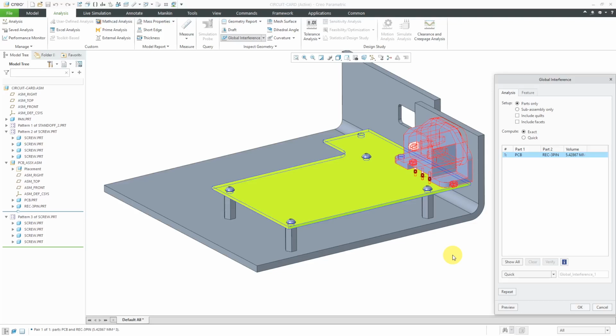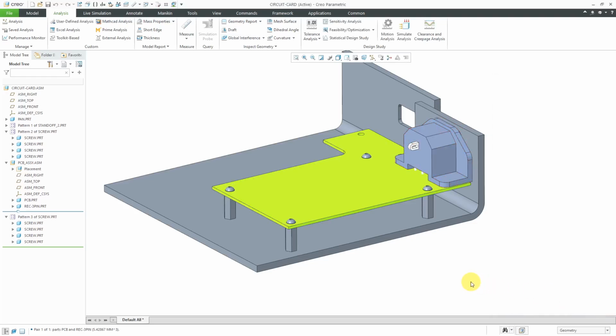Sometimes you want to perform a manual tolerance analysis by applying the worst case situations to the different dimensions in your model. And the way that you do that is by using what's called the dimension boundaries. First off, let's cancel out of here. And if you want to do anything with your tolerances, you need to display your tolerances on the screen.